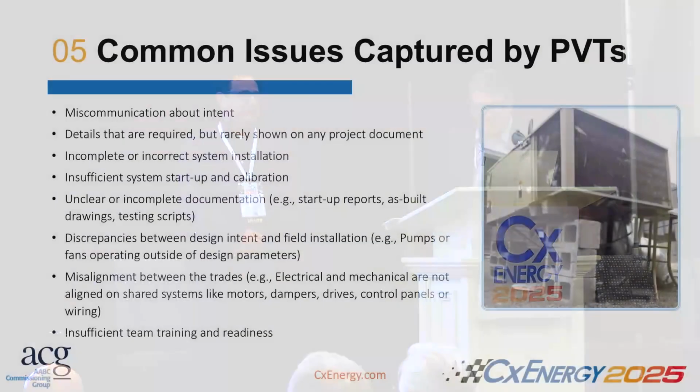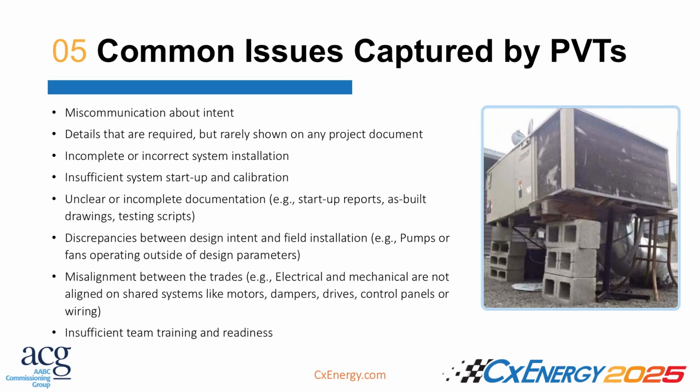I know on the electrical side, it's super critical that the arc flash report gets submitted before you energize and check the ratings of all the breakers, things like that. There's not one project that I've seen where we haven't found issues on. So again, the more eyes on everything beforehand, the better. It's a chance, and it's everybody, right? It's the whole project team, the CM, the GC, all the trades, the commissioning agents involved in it.